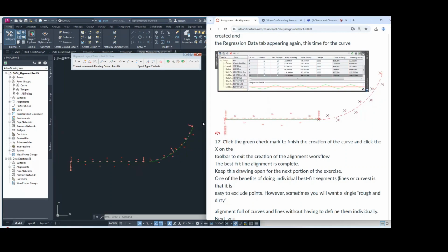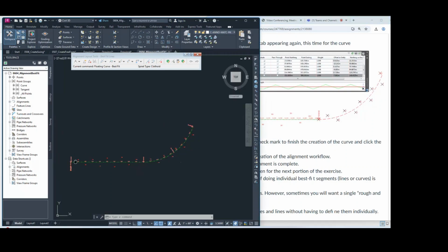So we tried 3 methods for selection. You can go to drawing and select them. You can type apostrophe PN when you have many points. Enter and then type your point number from the first number, dash, to the end number. Or if you have a group, you can select a group from the command bar and select your specific group.